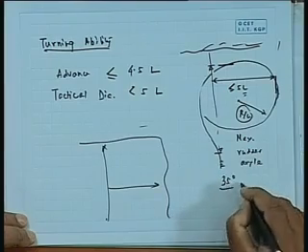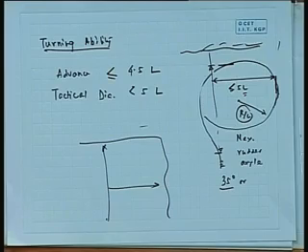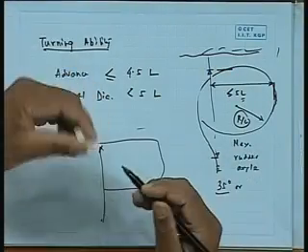Yeah, okay. It is basically 35 degree or the maximum rudder angle that is permissible. Normally most ships is 35 degree. There is a reason which next lecture will tell you, because that's where the angle of stall occurs mostly. So that's why you have it that way. But we cannot have a radius smaller than this. We'll have more than this only. This is a stipulation that says 35 is specific, the radius it will make.